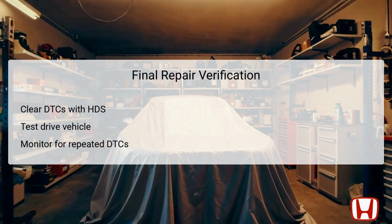Following the completion of all necessary repairs, clear the diagnostic trouble codes using the Honda Diagnostic System, HDS, to reset the vehicle's status. It's crucial to perform a test drive to ensure the repairs have resolved the issues successfully. Observe for any signs of repeated DTC occurrences or abnormal vehicle behavior during the drive. This verification step is essential to confirm the successful restoration of normal function and ensure that no further intervention is immediately required.